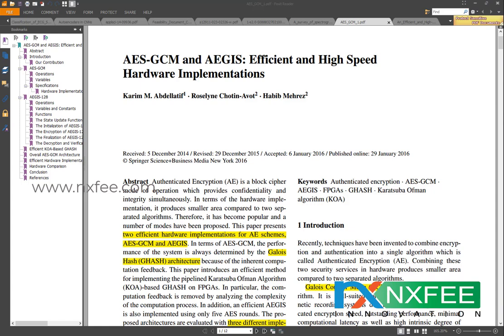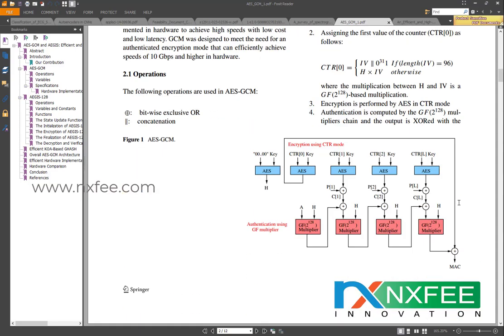So this paper presents the AES-GCM architecture. Here, Figure 1 shows the overall system architecture of the AES algorithm with GCM. The total plain text is covered with 512 bits. Depending upon the requirement, we can choose a different number of bits. For our purpose we chose 512 bits, and 4 AES 128-bit architectures are used internally, covered 4 times in parallel.